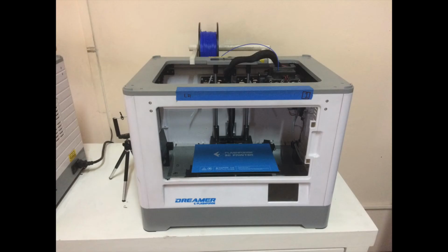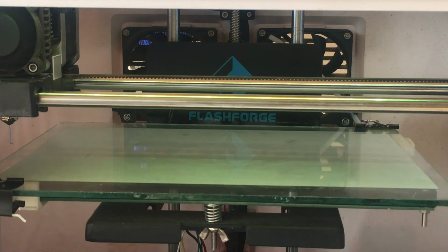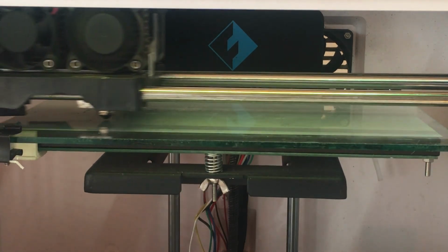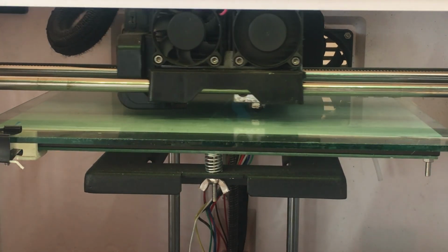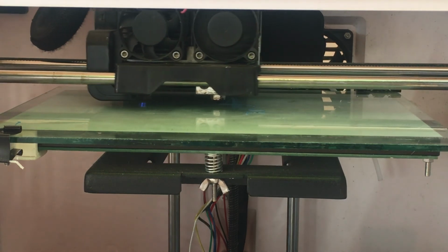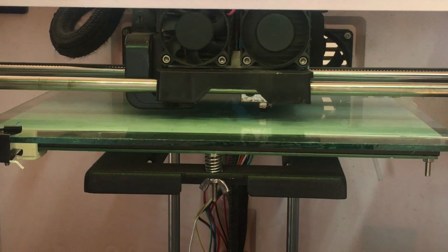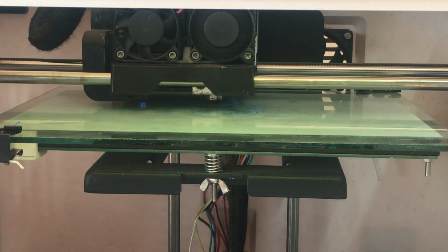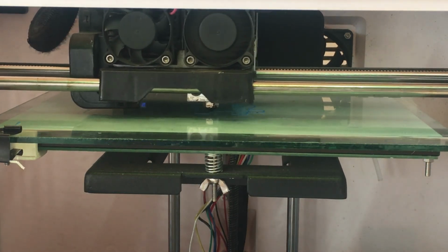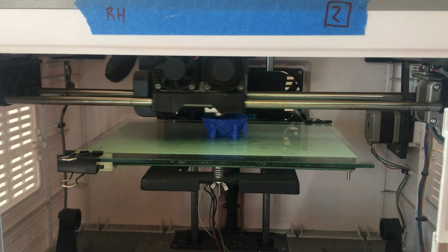We will print the owl with this printer, and as you can see, the coil is already charged with a PLA material that is blue. Here you can see some sections of the actual printout. In total it took about 2 hours to print the entire owl with a layer height of 0.28 millimeters. The printer first prints the outer wall and then fills the inside with a kind of grid. Here we made the video about 4 times faster.